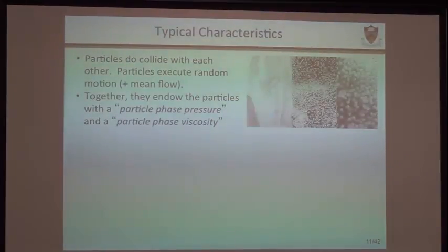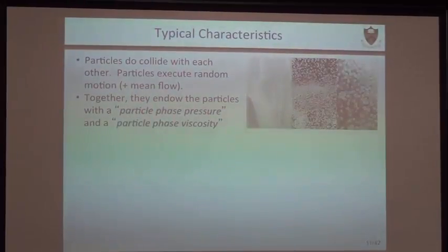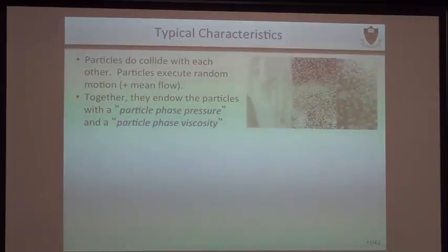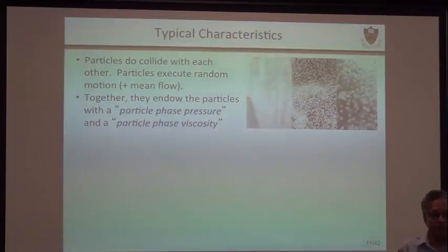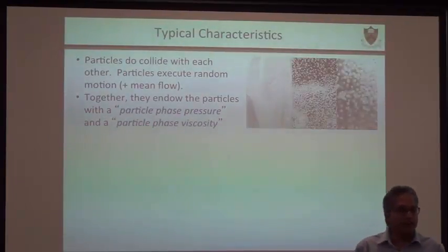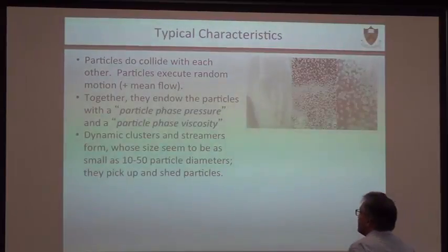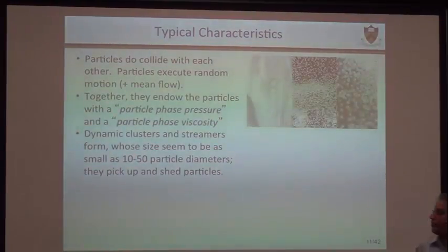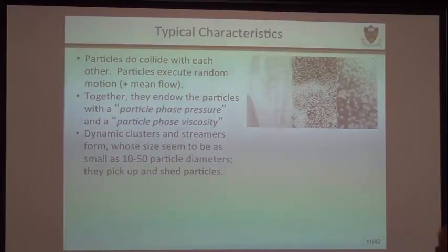And so these random motions give the particles an effective particle-based pressure and an effective particle viscosity, so we can begin to think of them from a continuum perspective with the average over the granular material. And these structures of the order of 10 to 50 particle diameters, they pick up particles, they shed particles, and this is realistically what's happening in these flow problems.